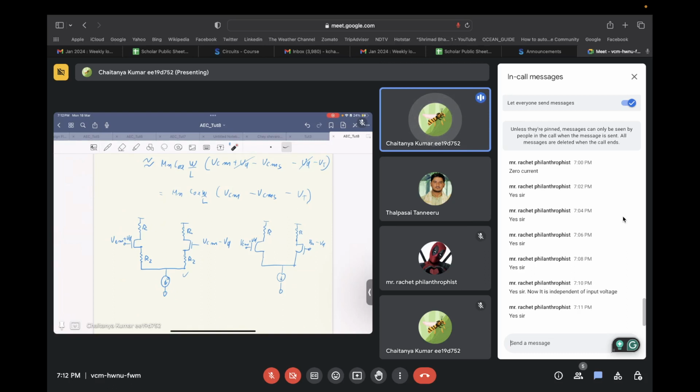That means the VDS this transistor would have got in the original circuit is much larger than the VDS it gets in this circuit. So the voltage headroom that this transistor and this current source have has now reduced. Can you think of a workaround to have this resistance R2 and at the same time not have the reduction in voltage headroom?